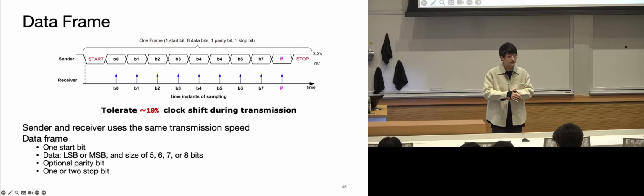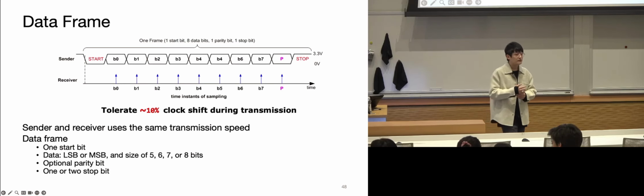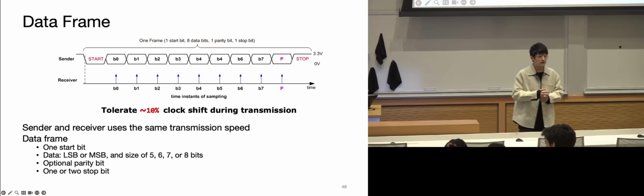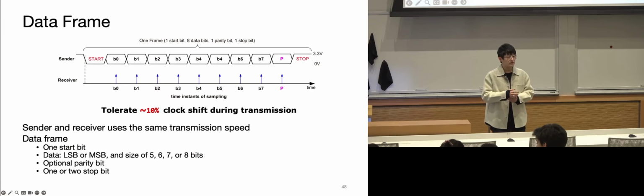If we sampled before the middle of the bit, we could have a longer string of bits, assuming the signal is stable enough. Did you understand what I'm saying? You're saying there is accumulated error between each bit? For example, they say the maximum advisable drift is like 5% per bit. Since we have 8 plus 1 from the start, so 9 bits, that's 45%, so it's 50% plus 45%. So the worst-case phase shift at the last detection is at 95%, almost at the other edge.